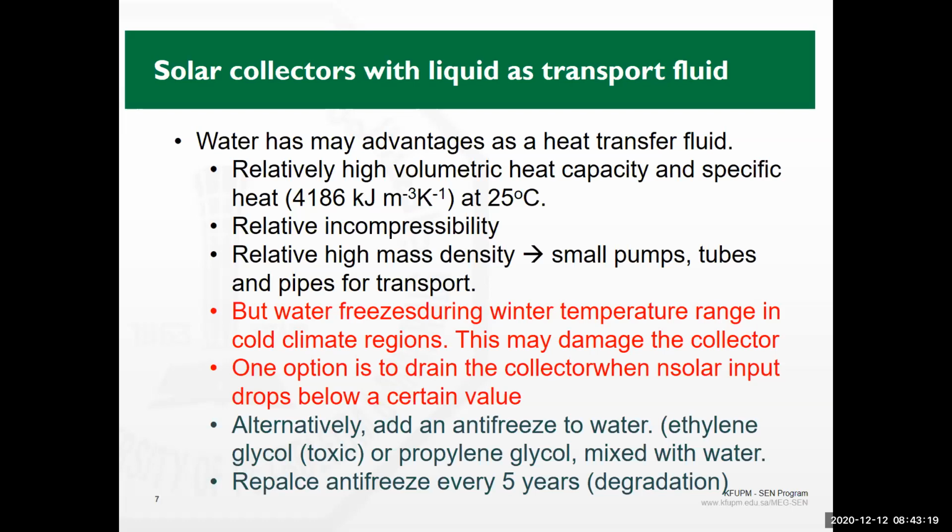Air can be heated very easily. I have solar collectors at the beach. They are basically evacuated tube solar collectors, at our beach here, KFUPM Beach, in our research area. So it's very easy through the collectors. I'm using 8 collectors, and then you can easily get an air temperature of 100 degrees centigrade, very easy.